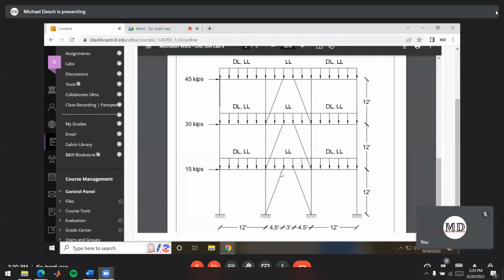And another benefit of this is that this little beam in the middle between the braces is sometimes called a fuse. This can be a good detail for some seismic design. The way these would deform would absorb a lot of energy, and it's a nice controlled way to control how your building responds seismically.